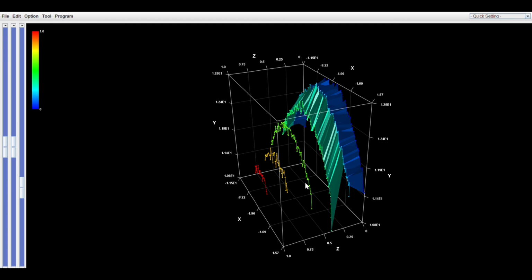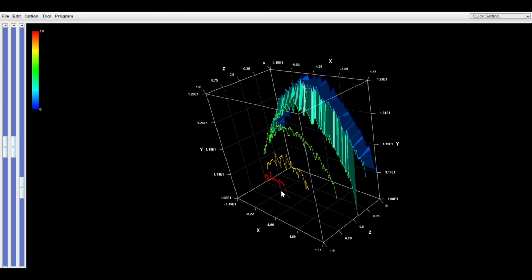Now if you choose streaming, it is a lot of data to handle, so all of these X and Z values will be constantly pumping out from the sensor, and you need to timestamp that and synchronize it with the Y that you're providing from the encoder or the robot input, to then be able to simulate the data and plot it all together in those specific slices.